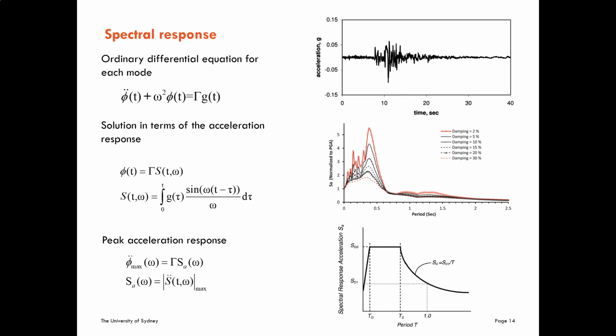And for earthquakes, the response is averaged over many earthquakes and is simplified by these expressions. Here it is assumed that the response decreases with the period. Here it is assumed that for small periods the response will increase linearly, and that there is a minimal and maximal period where the response is approximately the same. So this is an approximation to these expressions, averaged over many earthquakes.